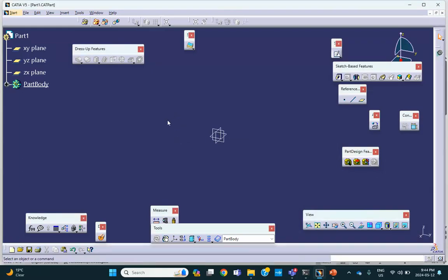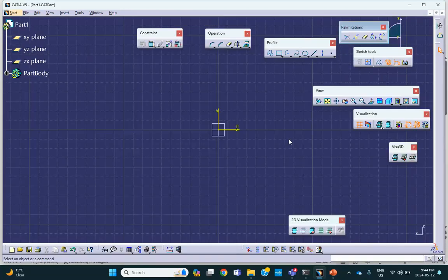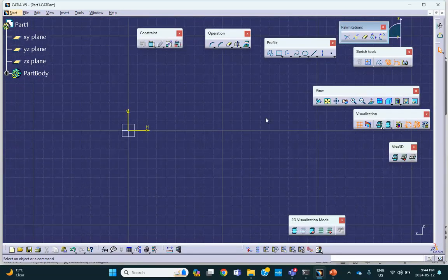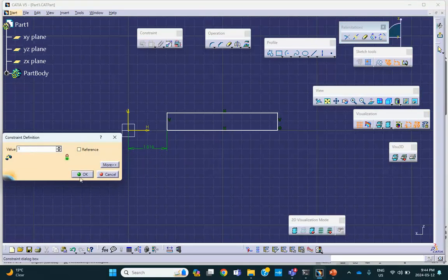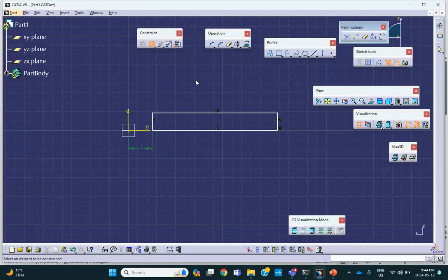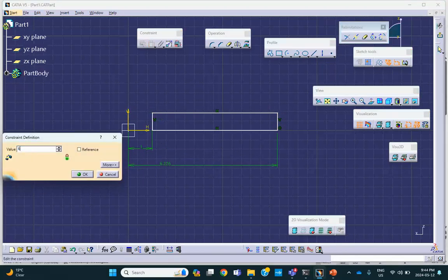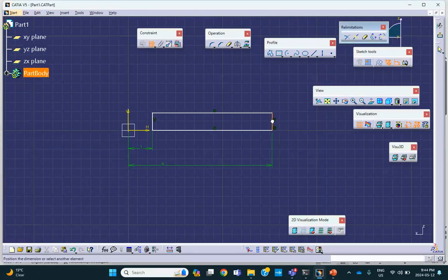Okay. So on the vertical plane, I will sketch. Remember, my first try is just to take half of the thickness. So I'm going to draw a rectangle like so, and I'm going to put some dimensions. So where are the dimensions here? The distance from there to there is 1 inch. That's the inside radius, the radius of the inside hole. And the dimension from here to here is 6 inches. That's the outside radius. And the height is half the thickness, 0.5.